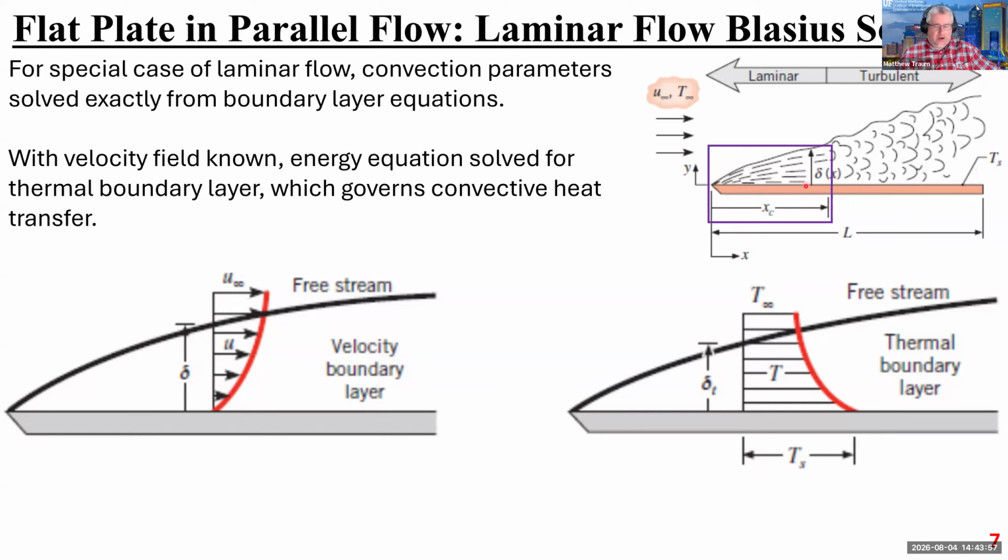So this is well organized, non-chaotic flow that basically happens in layers, for which the solution is known, the Blasius solution, as I just mentioned. At some critical Reynolds number, called the transition Reynolds number, all of a sudden the flow trips from laminar to turbulent. That's what's shown here.